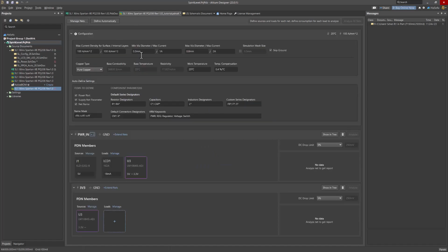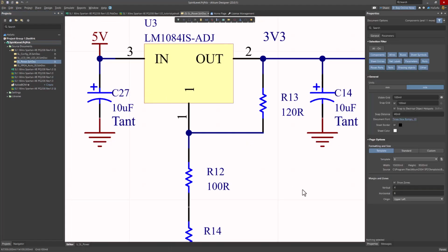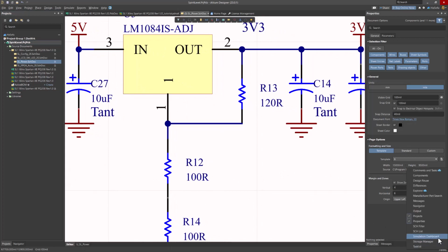So click back on the PDN analyzer. We have a couple other devices that are on this main top side of the power tree. So I'm going to add those. Let's add R1 resistor. How do I know that I need to add R1? Well, let's go ahead and save this. Go into power, and I like to use the feature in Navigator.